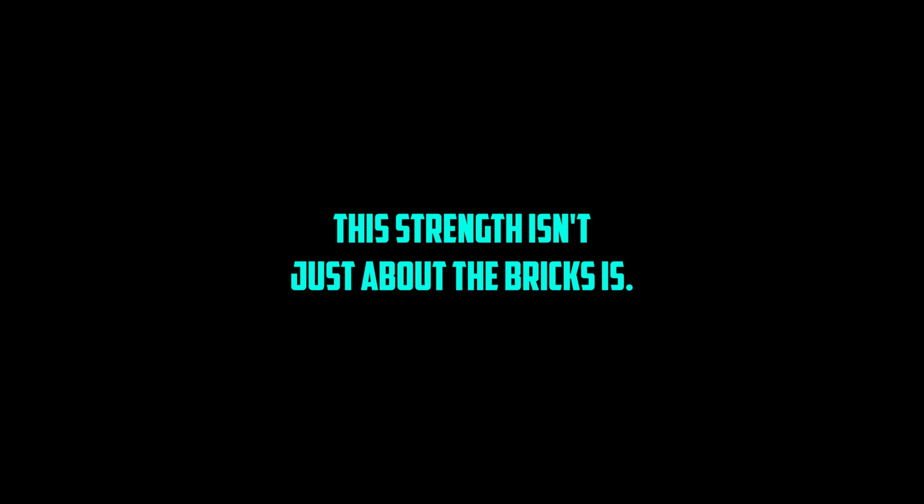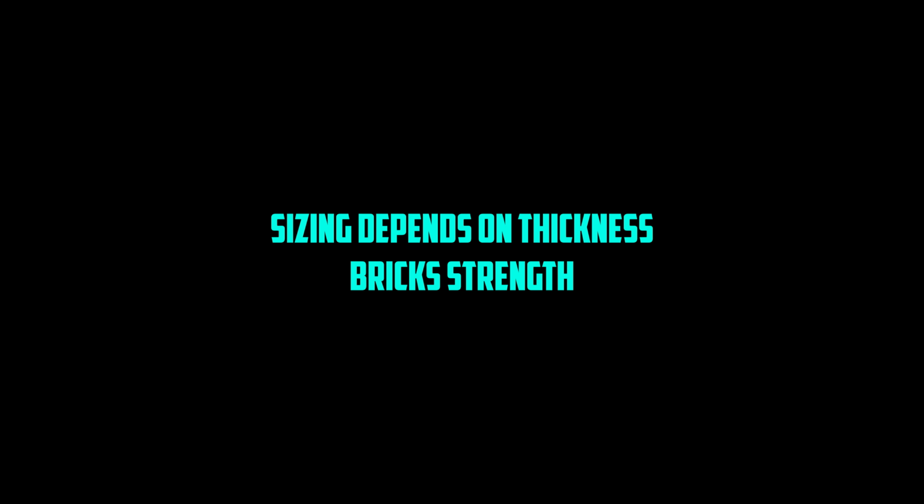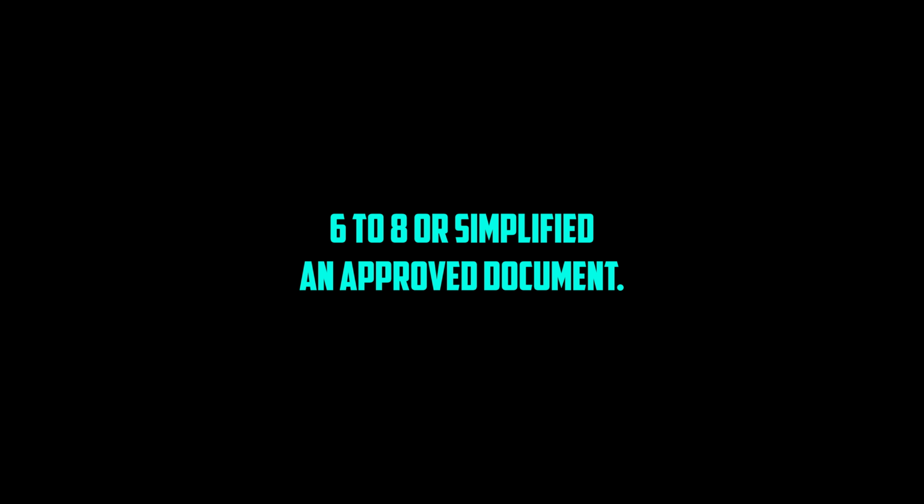Load-bearing brick walls, this strength isn't just about the bricks, is it? No, definitely not. Sizing depends on thickness, brick strength itself, which varies massively, mortar strength, how tall and thin the wall is, slenderness ratio, and whether the load is applied centrally or off-center, eccentricity, all covered in standards like BS 5628 or simplified in Approved Document A.